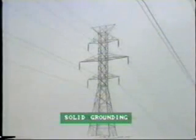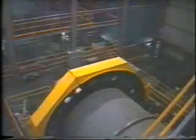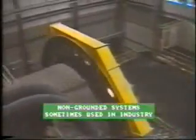Now, at this point, let's briefly summarize the methods of grounding which you will encounter. Solid grounding. This is the case with most utility systems above 40 kV. Generators may be grounded through an impedance so as to limit the magnitude of fault current. Non-grounded systems are sometimes used in industry where a continuous power supply is required.